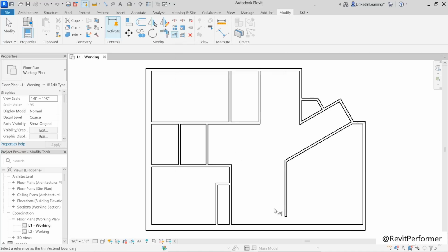So instead, I'm going to shift to this trim and extend command. This one is a little bit different because you pick a boundary edge first. That's what you want to extend or trim to, and then the element you want to trim and extend. And in this case, it won't create an L condition, it'll create a T condition, and that's more appropriate for this situation. So let's click the Modify tool to cancel out of there.